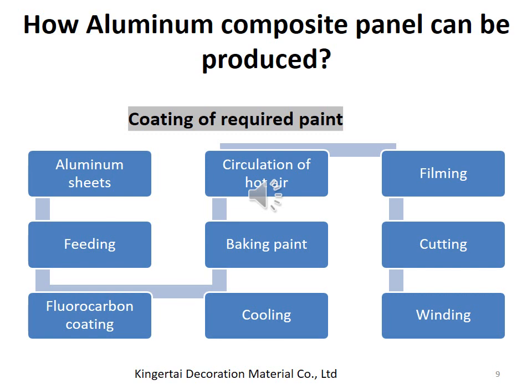Aluminum composite sheets are coated with 2 layers of paint and primer. The top coat of the facade is a highly weather resistant fluorocarbon resin coating, namely polyvinylidene fluoride. It has excellent UV protection and pollution resistance, which keeps the surface of the protected aluminum coil beautiful. The surface of the aluminum composite panel can have not only the color of the metal but also a beautiful marble pattern and color.